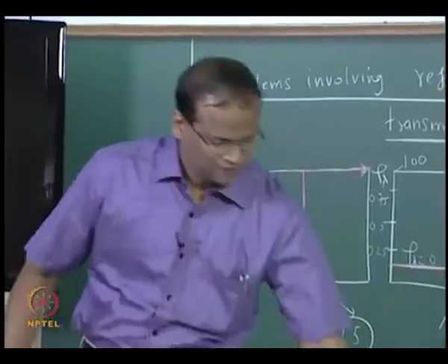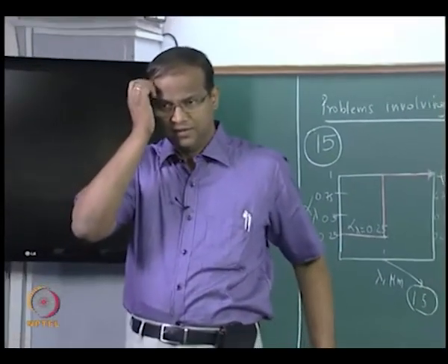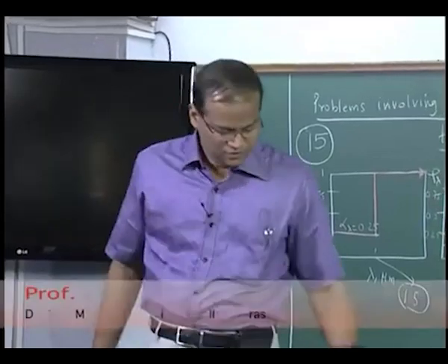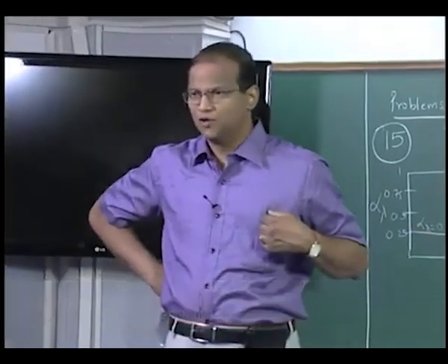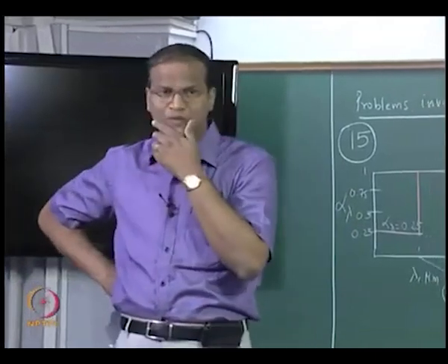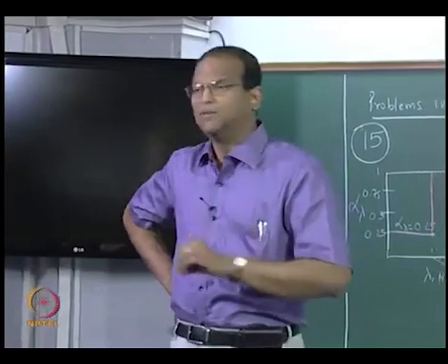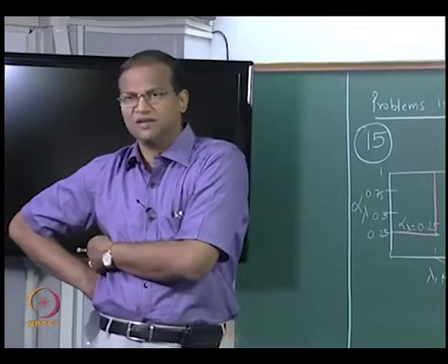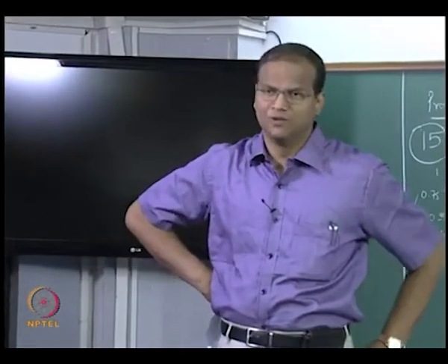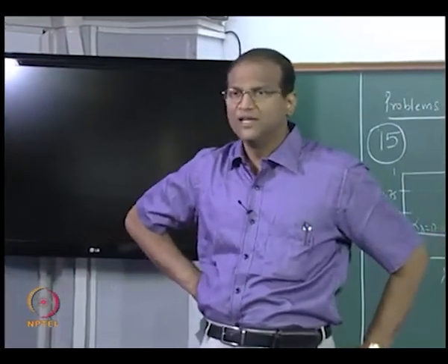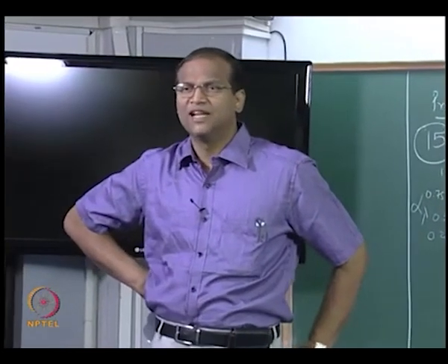Okay, so we looked at transmissivity in yesterday's class, and there can be surfaces or media which are non-opaque, which will allow some radiation to pass through. When radiation passes through such non-opaque media, generally they are participatory in nature, because there can be emission because of the temperature of the medium being greater than 0 Kelvin according to Prevost's law. It can also absorb, it can also scatter. Scattering is basically reflection, but scattering is from the volume.